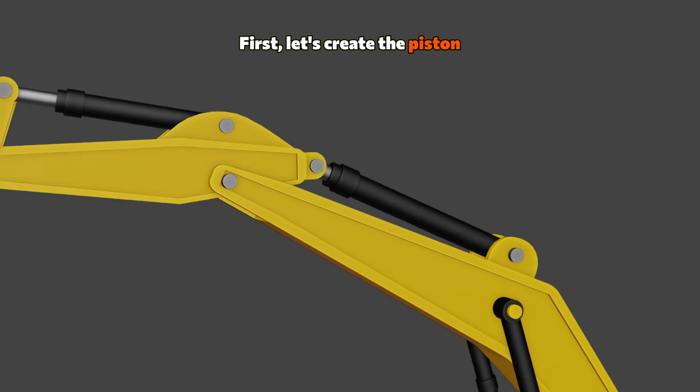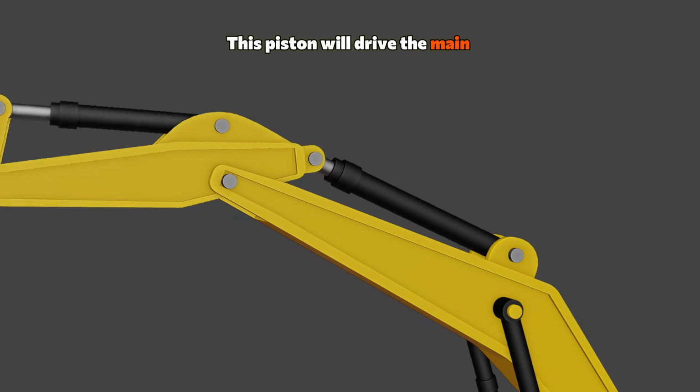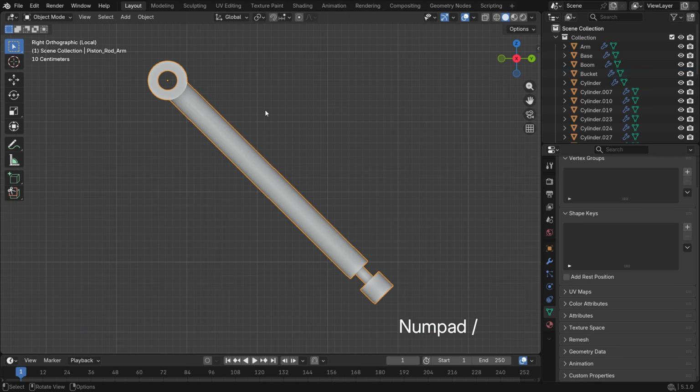First, let's create the piston that controls the opening and closing of the arm. This piston will drive the main movement of the arm. Go to Object Mode, select the piston rod, and press numpad slash to isolate it.